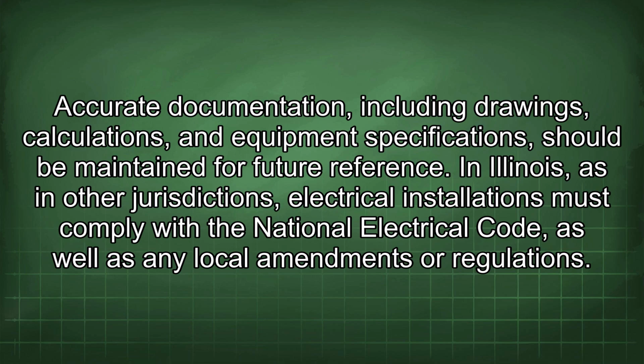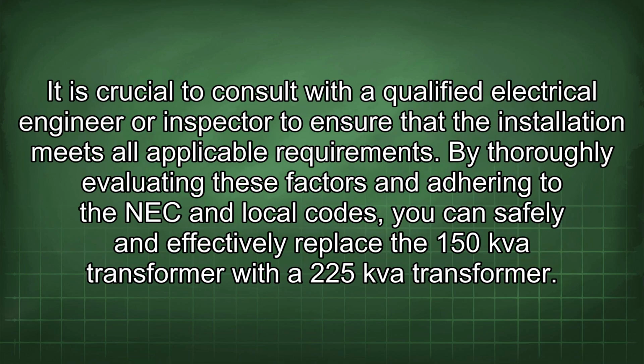In Illinois, as in other jurisdictions, electrical installations must comply with the National Electrical Code, as well as any local amendments or regulations. It is crucial to consult with a qualified electrical engineer or inspector to ensure that the installation meets all applicable requirements. By thoroughly evaluating these factors and adhering to the NEC and local codes, you can safely and effectively replace the 150 kVA transformer with a 225 kVA transformer.